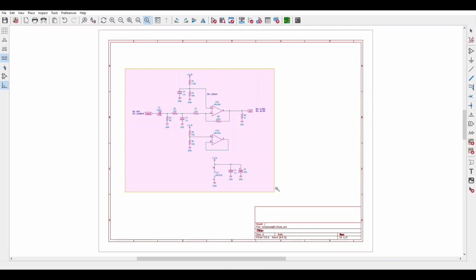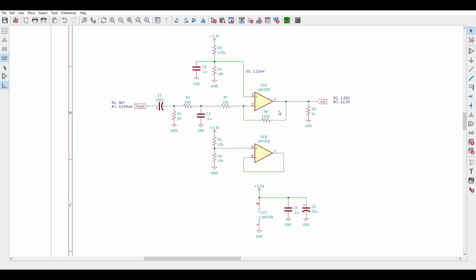Now this guy can certainly do variable amplitude, variable frequency, and an adjustable DC voltage offset. However, there's another problem here. I could easily overload the input of that Nano if I wasn't careful and fry that particular channel. So a safer method would be to come up with a simple op-amp buffer circuit between the Simpson and the Nano, and that's exactly what I'm going to do. Here's what that circuit looks like. I don't need a sophisticated op-amp here. The generic LMV358 will work just fine. It'll operate from a 3.3 volt single supply, it's rail-to-rail output, and the rest of its specs are definitely compatible with this simple experiment.